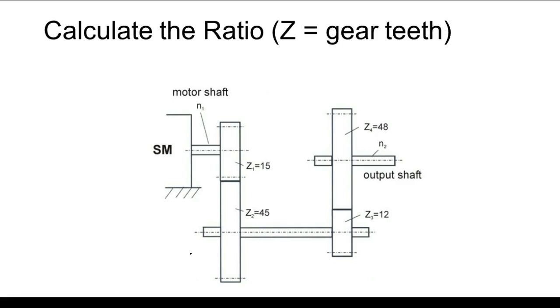Okay, so here I'm going little to big, here I'm going little to big. So anytime you go from little to big, you're a torque multiplier. When you go from big to little, it's a speed multiplier.